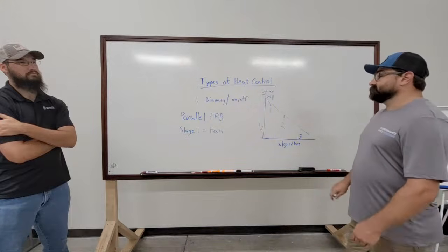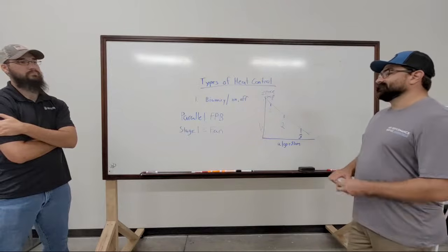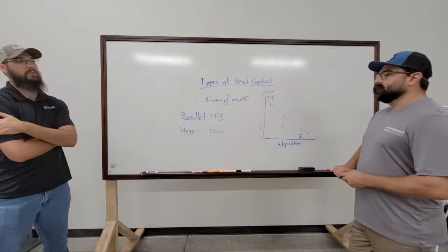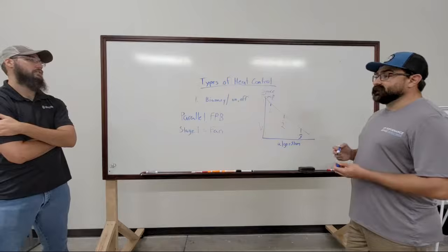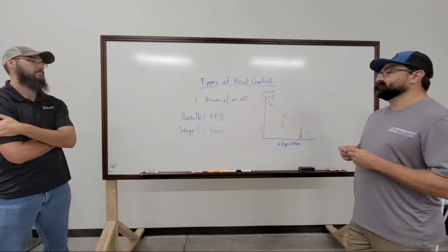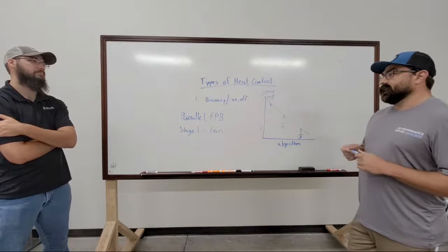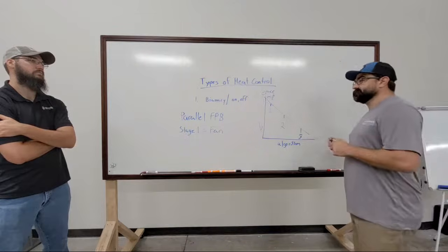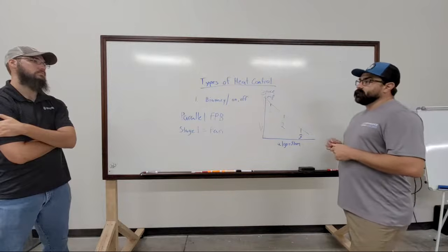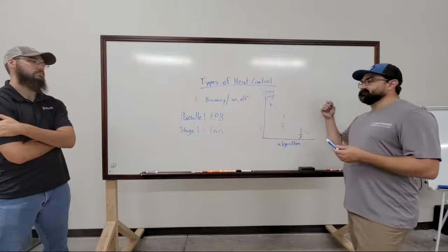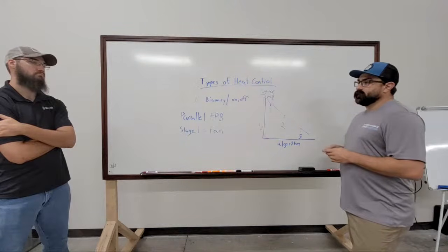We do have cutouts where we will cut them out at a certain discharge temperature, but we don't maintain a set discharge. I've run into a few. Once it goes into a heat mode, it will try not to go over a certain point. Like it'll have a high temp cutout. That can either be an internal safety where it will actually drop out the contactor, or, in the case of a modulating output, we actually start to drop that back down to maintain that certain temperature.